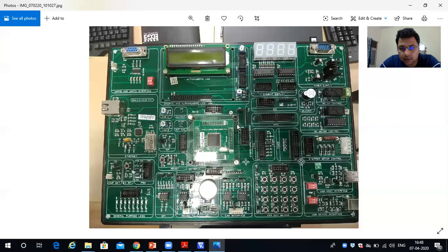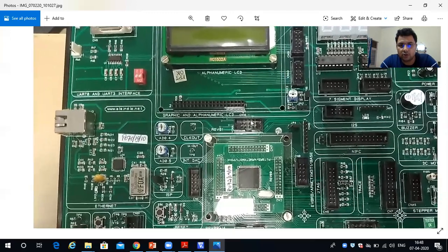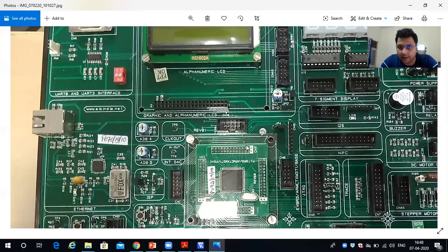Likewise, we have 4 connectors. This one is C and A, where you can see C and A. This is one connector which will connect these core pins, the microcontroller pins, with our peripherals. This is C and A. 8 pins are used, total 10 pins, but 2 are not going to be used for signals. Those are for power supply: one is ground and another is VCC, meaning plus 3.3 volts.